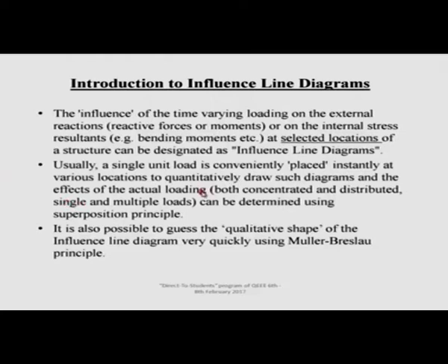So, usually a single unit load is conveniently placed instantly. I say instantly just to give an equivalent static effect at various locations to quantitatively draw such diagrams, and the effects of the actual loading, both concentrated and distributed, single or multiple loads, can be determined using the superposition principle.